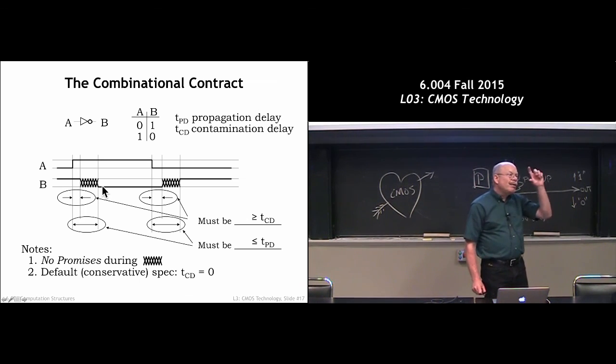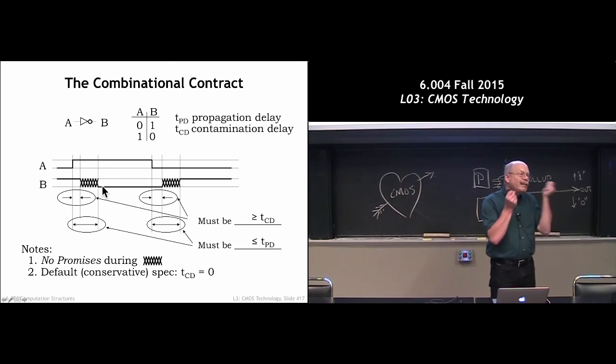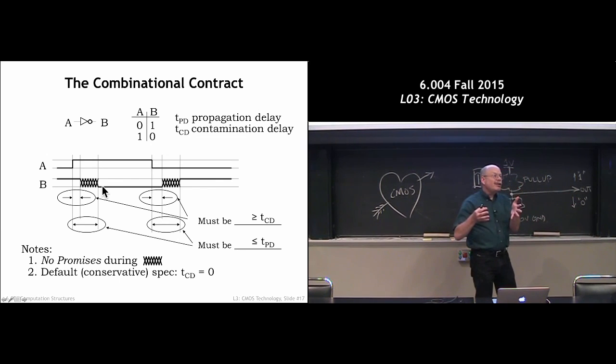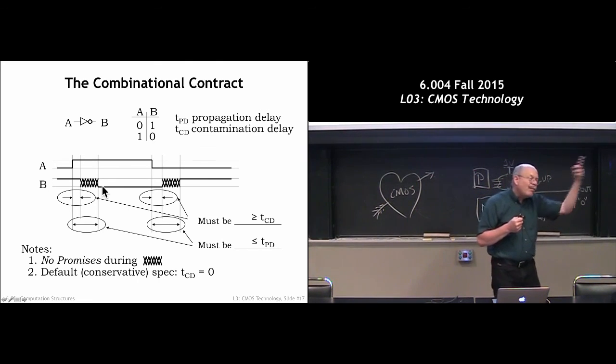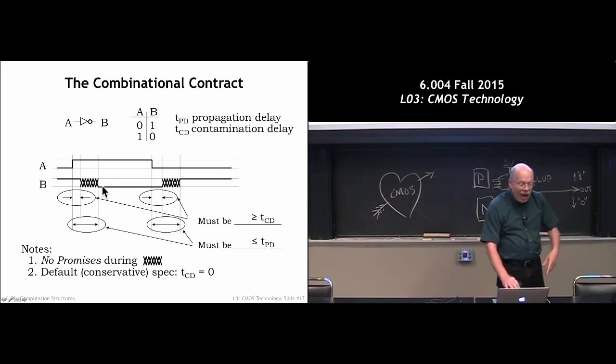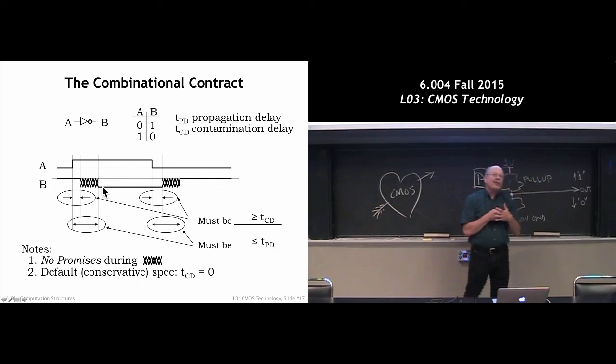So these two timing numbers tell us the timing specifications for the gate. So between the functional specifications, which we often get from a truth table, and these timing specifications, and the digital signaling spec, we actually have all the elements of the static discipline that we needed to build combinational devices. In fact, we can build very large combinational circuits out of combinational components and use the technique we discussed last time in lecture to write down the static discipline specifications for our new larger synthesized combinational device.